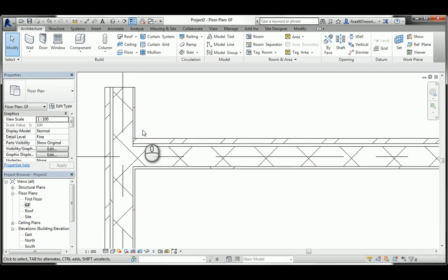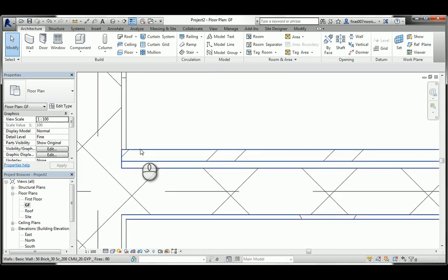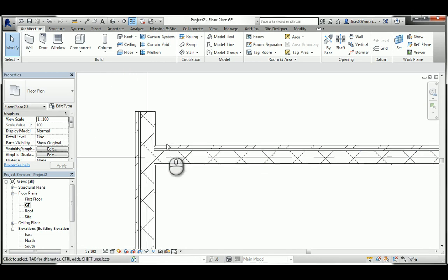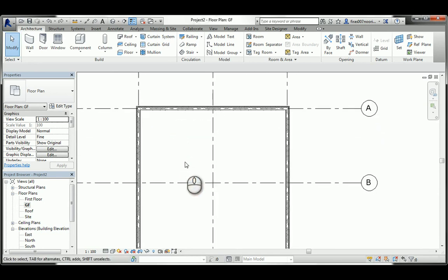and you're gonna see again that's number 1. That's number 4, so it has higher priority than this one, which is number 5. So number 5 with number 5 will have a full trim. That's so clean it is. But when you have number 4 and this is number 5, again it's going to show you a line, and this one will have the priority to go through and touch number 1, while this one will be trimmed. And that's because this is 4 and that's number 5. Anyway, I'm going to try to explain that more in a further related lecture. So that's my walls.